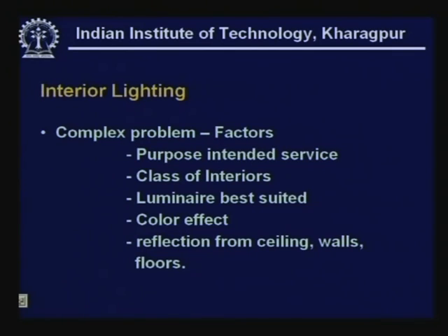Then is the necessity of looking at the luminaires. Now, depending on the height of the building or the interior, one can look at, and based on the application, let us recall that a point source of light essentially has illuminance reducing inversely as 1 over the distance square, whereas if you had a line source of light, it reduces inversely as the distance.